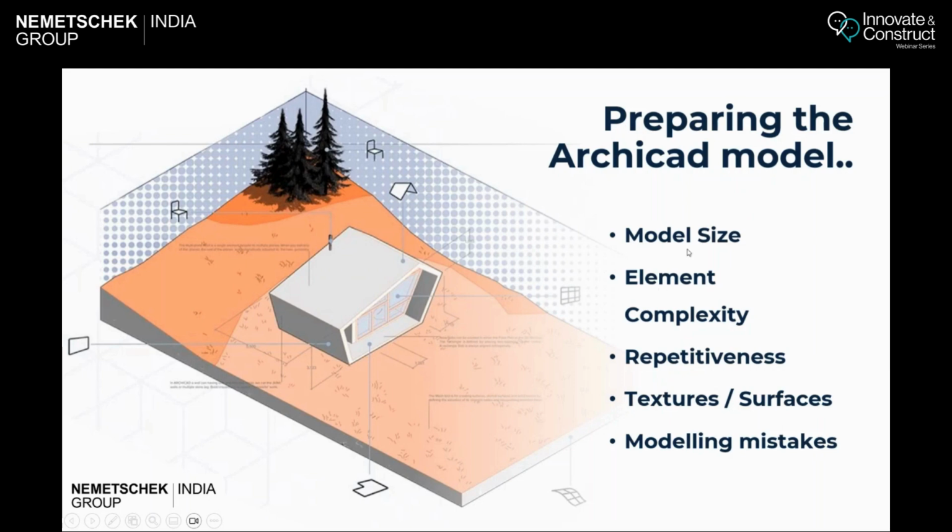So let's see what are the prerequisites to export a good BIMx model. These are the factors that affect the complexity, and for a good BIMx model, we'll have to check the model size and the element complexity and the repetitiveness of different elements that we place in our project file, the textures and surfaces, and modeling mistakes. So these are the factors that we should check before we export a BIMx model.